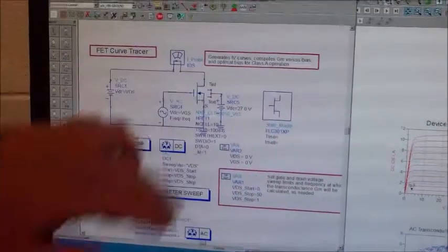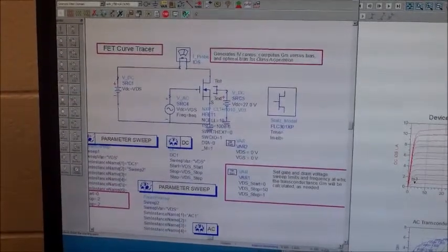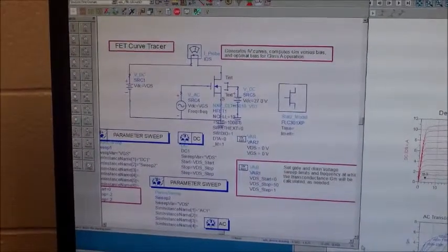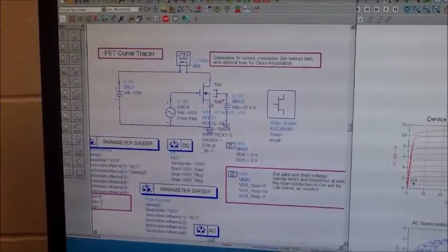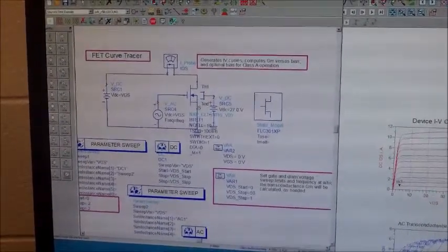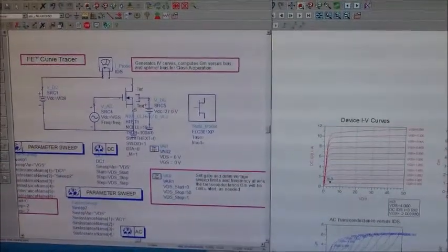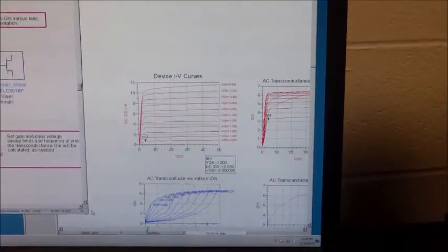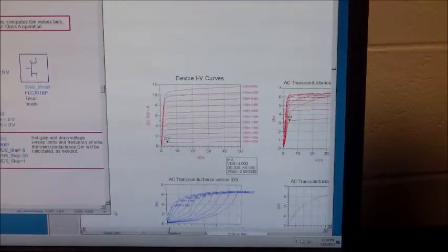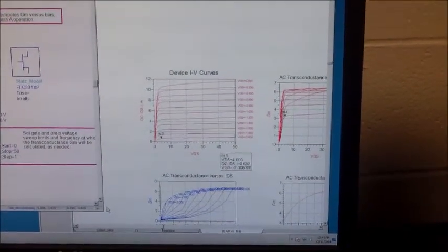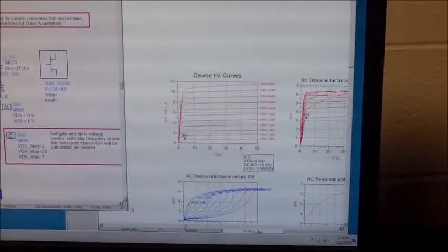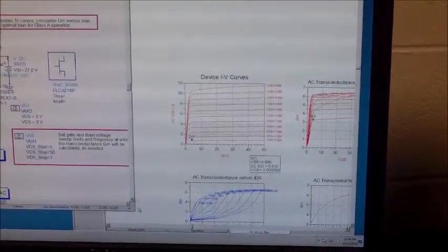And if you'll step right over here with me, this is the GaN. Again, right here is the GaN transistor in basically the same setup with altered parameters. As you can see, we're going from 0 to -2 in steps of 0.2, and again, we're going from 0 to 50 in steps of 1. You can see the results right here. There's basically no compression across this, and we are reaching a considerably higher level of power across this system, which is what you would expect from a GaN transistor.